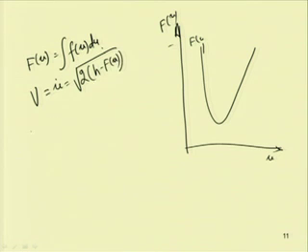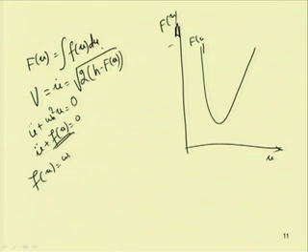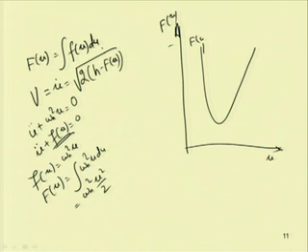For example, in case of the spring mass system, I can write this equation in this form: u double dot plus omega n square u equal to 0, or if there is some forcing, then I can put it F cos omega t or F sin omega t. So, then u double dot plus f u equal to 0. In this case f u will be equal to omega n square u, and this capital F u will be the integration of omega n square u du. So, this will become omega n square u square by 2. In this way one can find this F u. After getting this F u, one can substitute it in this equation of velocity, that is u dot, and find what will be the velocity for a given value of u.